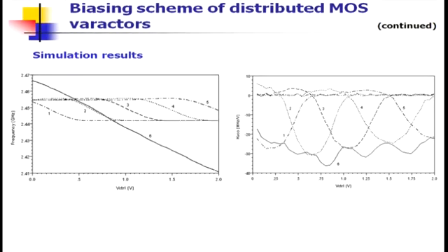So, all the capacitors are being added in parallel and they are varying. In that case, what will happen? Each will have tune and the next one will tune like that. So, immediately you will have a continuous tuning range, a wider tuning range, where KVCO will be much lower. That you are seeing from that signal, because my target is low power consumption and to improve the phase noise performance. So, we have introduced arrays of such varactors to reduce the KVCO.